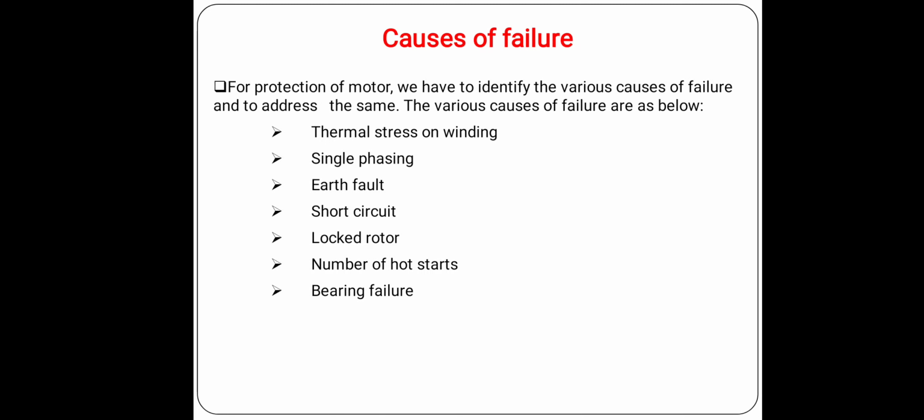Next one is number of hot starts. We can explain this as: each motor is designed to withstand a certain number of hot starts. Now consider a motor is in running condition. If we stop the motor and immediately start the same, then this is called a hot start.